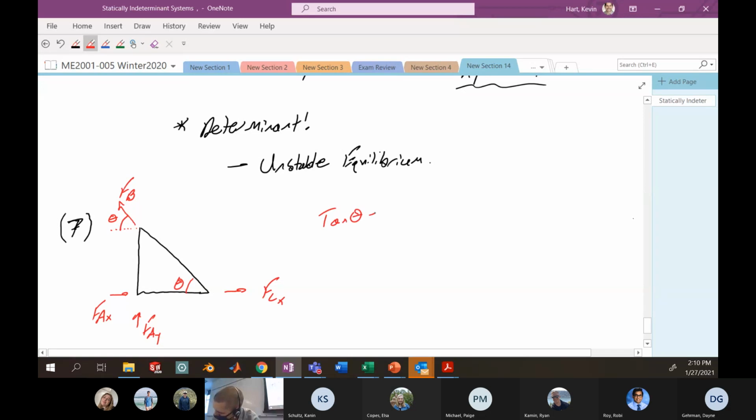And we have a situation where the angle is the inverse tangent, we know the side length is 9, the side length is 12. This gives us an angle theta in this particular situation, which is going to be 36.9 degrees. All right. So now let's go about trying to work through this bad boy. Okay. Can't forget my force P here. I got to think, is this statically determinate or not? Well, it looks a little suspicious, but maybe we can figure this out. Okay. Did I draw that right?